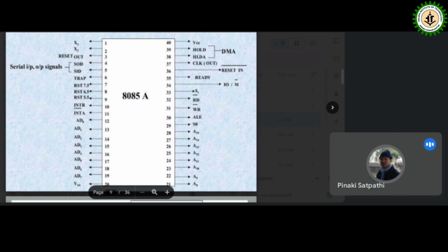It is an input signal coming to the microprocessor. Some peripheral devices are very slow and unable to follow the speed of the microprocessor. To slow down the microprocessor, this particular signal is used. If the peripheral device is not ready for data transfer, this signal goes low, and no data transfer will be possible. The microprocessor will be in a wait state.